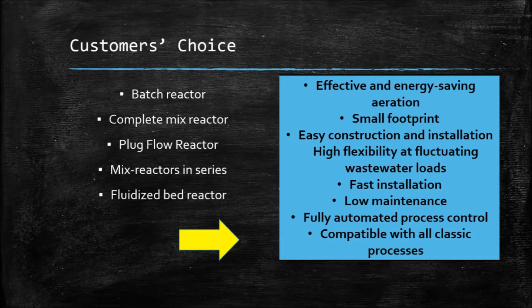However, all the mentioned reactors should be able to fulfill these requirements, which are effective and energy-saving aeration, small footprint, easy construction and installation, high flexibility at fluctuating wastewater loads, fast installation, low maintenance, fully automated process control, and compatibility with all classic processes.